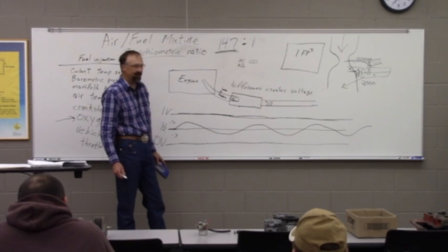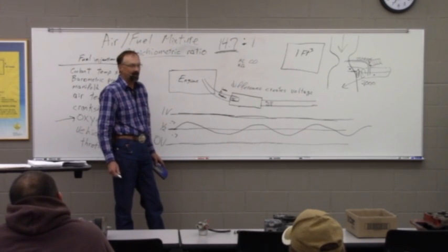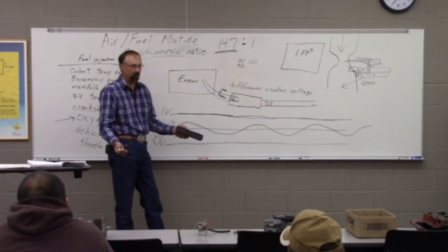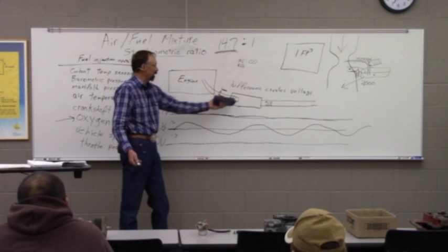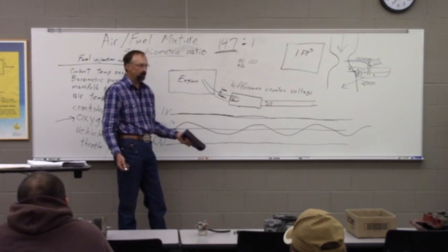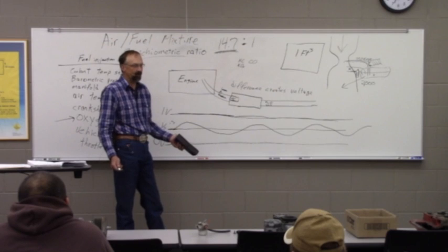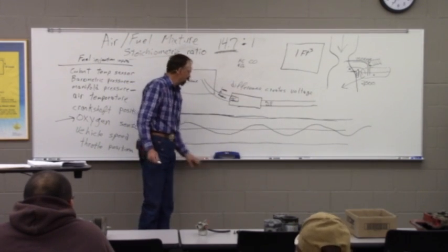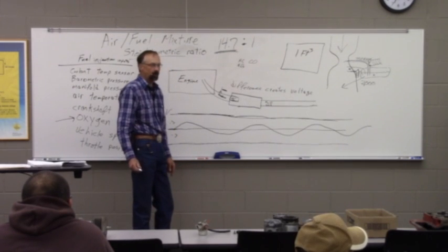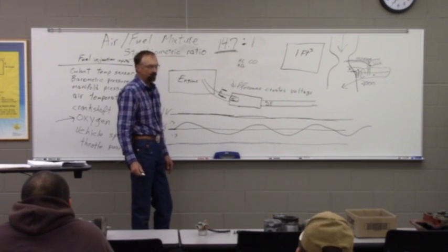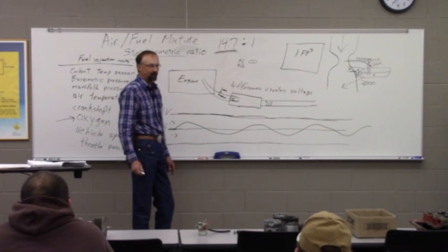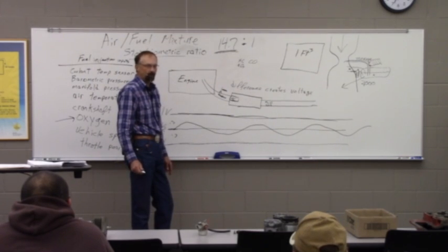And there again, they'll be incredibly hot, because the burn of the fuel, the combustion that we normally wanted to use in the cylinder, well, that burn is happening in here, and you get a lot of heat. It actually creates some really high temperatures. You can have 12 or 1400 degree temperatures there, and those have been known to start some fires, as you can imagine. You put cheatgrass against a 12 or 1400 degree can of metal, and you've got a grass fire, don't you?